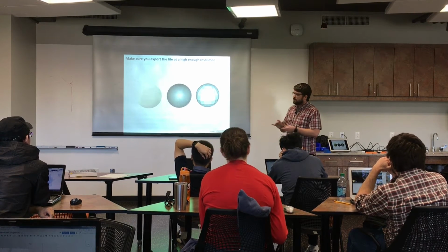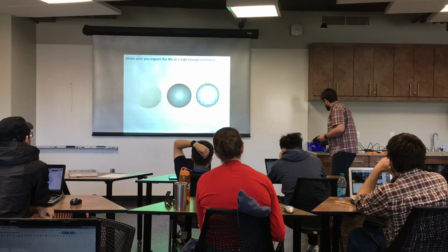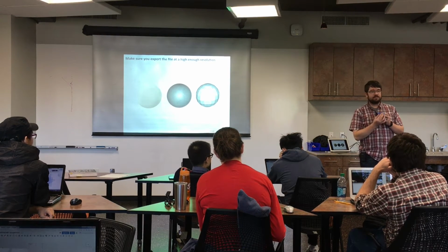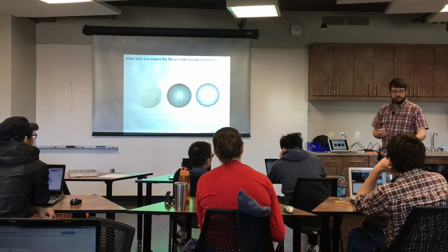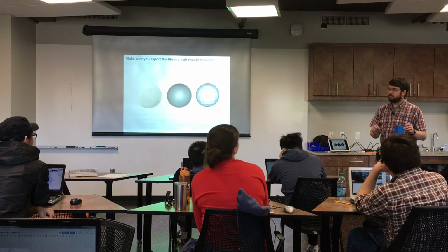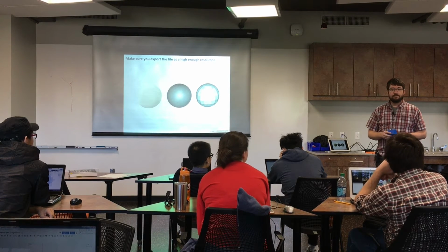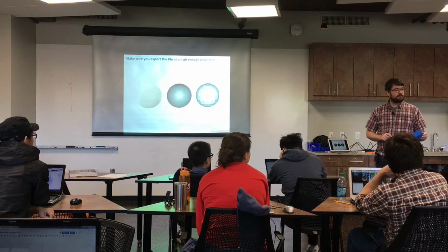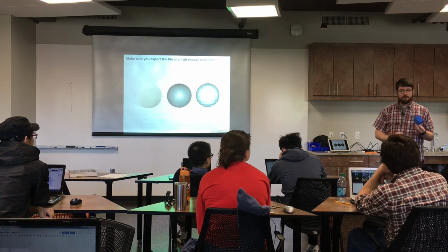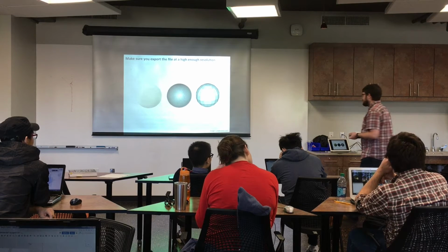And some of your parts, if they are a little bit rough, there is going to be some texture, just from the nature of having it 3D printed. You can put these in a box, spray some filling primer like you would put on a car on them, kind of shake it around the box, spray the primer. Do that a couple times, put a coat of paint on it, and nobody will know it's not a cast plastic piece.